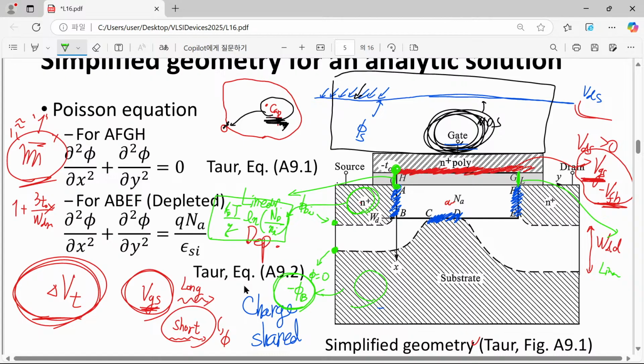That will be the potential for our N plus region. The difference between them is regarded as potential bending. So this quantity is regarded as built-in potential. Simply speaking, in this notation, phi built-in should be regarded as phi b plus kBT over q ln Nd divided by ni.